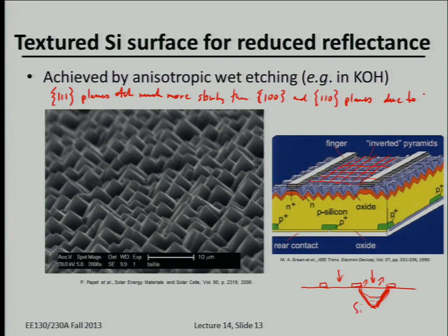Density. Yes. Surface energy. Oh my goodness. Okay. Yeah. So yes, it's true. The 111 plane does have a higher atomic density, you know, more closely packed atoms than, let's say, a 100 plane. That's true. But a 110 plane, if you remember from homework 1, is actually even denser. It has a higher atomic density.